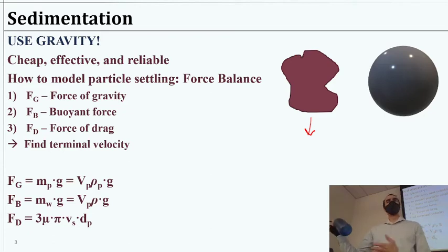And we have some empirical relationship with something about the particles, something about what's happening, and we derive some equation based on the observations. Here with type 1, which we're going to cover and use for this class, we can take it from a force balance of what forces are acting on a particle, assume it's spherical, and then we have a pretty nice equation that can account for different parameters.